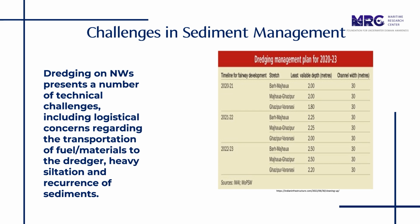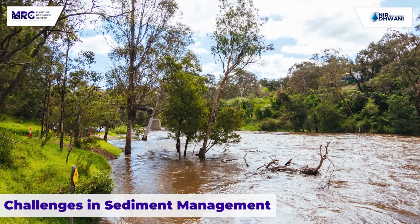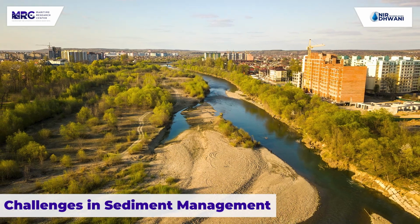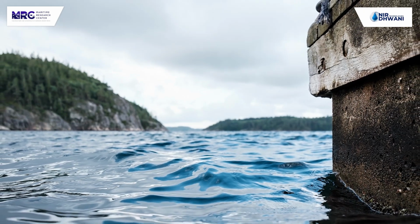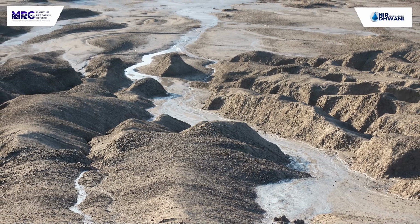However, the dredging on the national waterway represents a number of technical challenges, including the logistical concerns regarding transportation of fuel materials to the dredger, heavy siltation, and the recurrence of the sediments that are there. So, major challenges would include the increased flood risk in downstream areas, frequent changes in river courses, morphological issues, difficulty in identifying the disposal grounds, strong currents and rapid changes in water levels and reduction of flow discharges, increased bank erosion issues, and difficulty in maintaining the dredging depths in upstream areas.